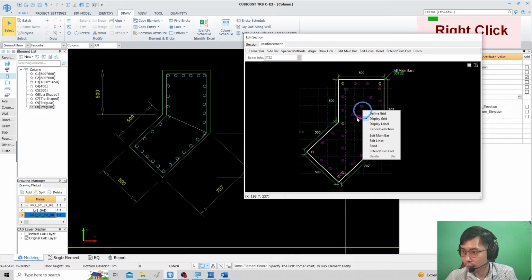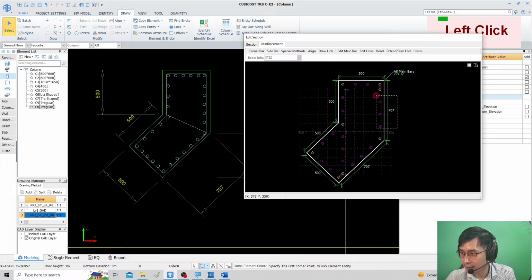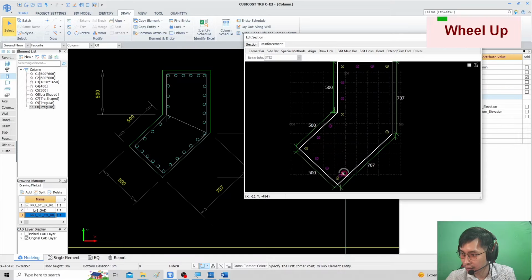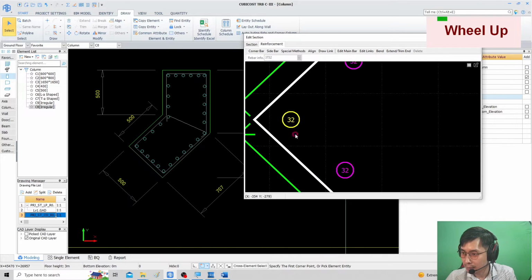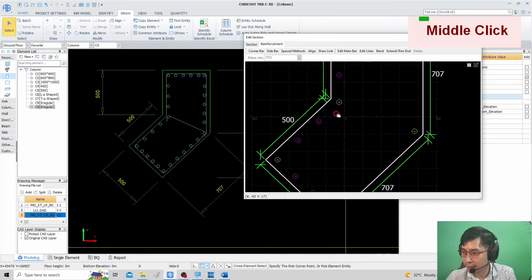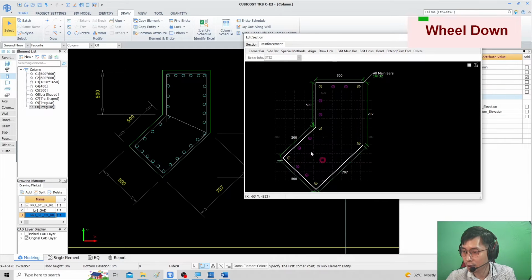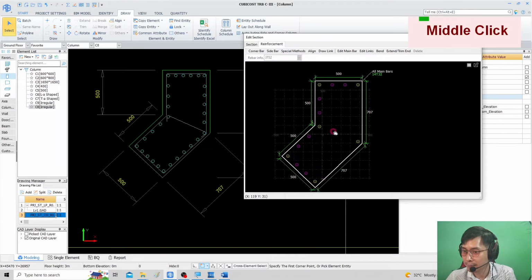The simplest way is that first, you have to delete those unwanted bars, just like this. Just highlight and delete those unwanted. The yellow color bar here means the corner bar, and the purple over here means the side bar. Actually, it's the same number, it's just that the software determines them as the corner and the middle side.